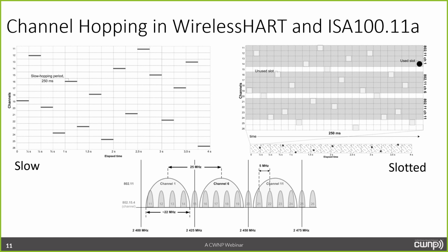So notice how we're not just hopping 11, 12, 13, 14, because then we're going to dwell for 4 slot times, or possibly 250 milliseconds times 4, all in channel 1, right? And so to avoid that, we have hopping patterns that jump around. Now, that sounds really good at first, but then when you think about it again, it basically means we're hopping all over the spectrum. So the reality is that even with measures that are put in place algorithmically and so forth to try to help avoid interference with Wi-Fi, or from Wi-Fi for that matter, there is still a reality of the possibility of interference.